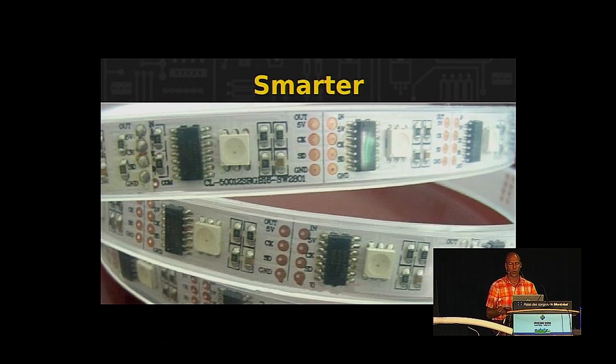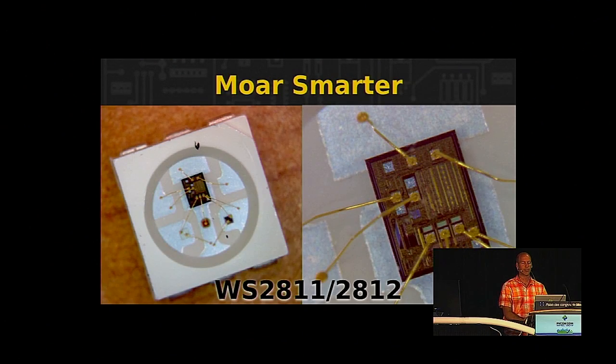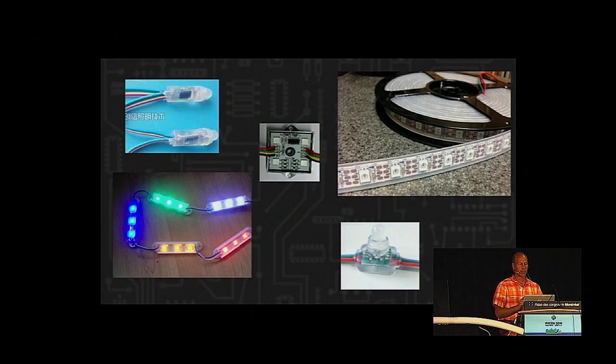Smart LEDs involve some sort of logic circuitry, some sort of integrated chip along the way that allows it to receive a data protocol, and each light along the strip can be individually controlled as its own color, its own brightness, etc. They've now gotten to the point where they're building these integrated circuits directly into the LED package. These require protocols, and there's a variety of them. But before I get into that, these packages come in different shapes and sizes. There are some varieties where there is more than one LED per control chip.